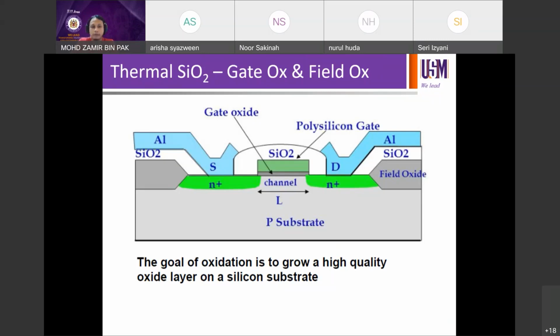So these can form either p channel or n channel depending on whether your MOSFET is p-type or n-type, and that p or n-type depends on the channel, right? Not on the wafers, but on the channel. So in this case, we're talking about n-channel MOSFET because your source and the drain are both of n types, right?